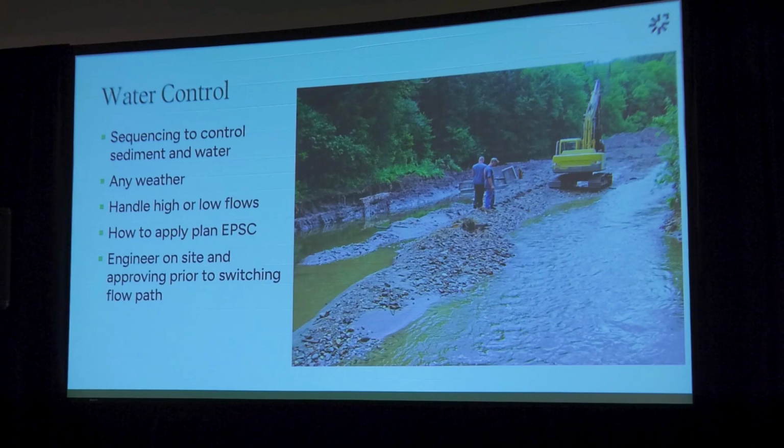And importantly, that last bullet, often the contractor will be trying to do work in the dry on one part of the site, maybe carving out the new pilot channel, and then there's a point where they have to switch water from one channel to another, and that's a really key time to be on site. Make sure that they're ready, make sure that there's erosion control in place, and so there's always going to be minor discharge when that happens, but we just want to make sure it's in a controlled manner and not just getting out of hand.